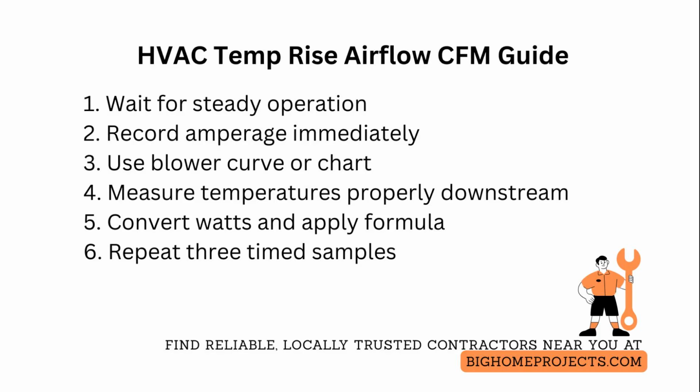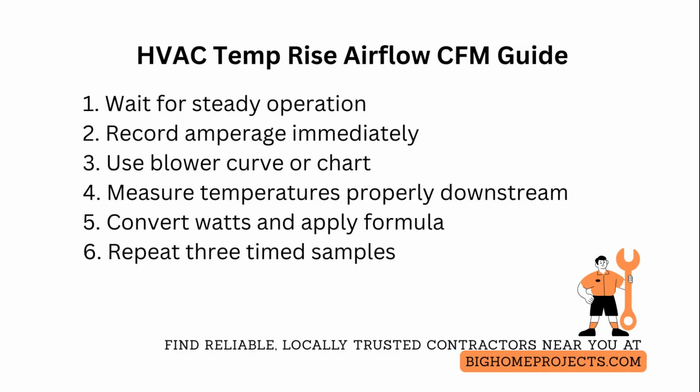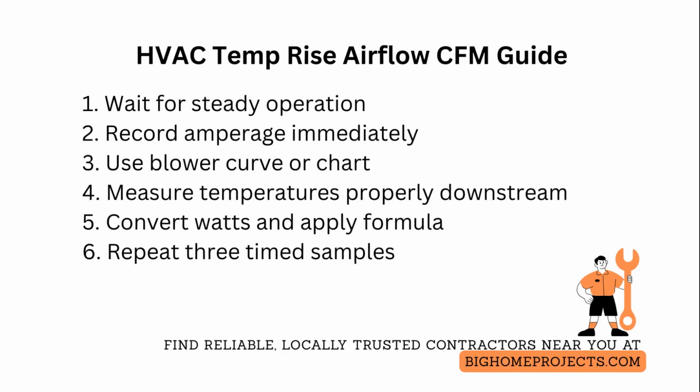so correct for those. Measure supply and return duct temperatures at least 6 duct widths downstream of any transition using probe thermometers pressed fully into the airstream. Average several readings and compute the temperature rise as supply minus return in degrees Fahrenheit.